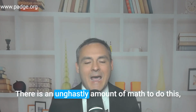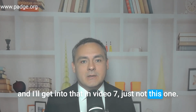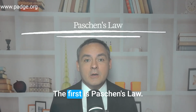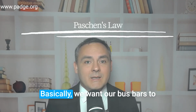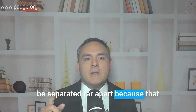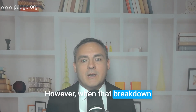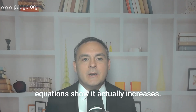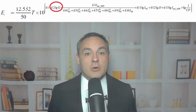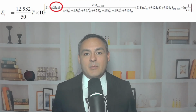There is an ungodly amount of math to do this, and I will get into that in video 7, just not this one. There are a couple of competing things going on with bus gap. The first is Paschen's law. Basically, we want our bus bars to be separated far apart because that reduces the likelihood of a breakdown. However, when that breakdown occurs, the incident energy equations show it actually increases. Look at the equation for incident energy. The takeaway here is you want to be accurate with your bus bar gap in your model.